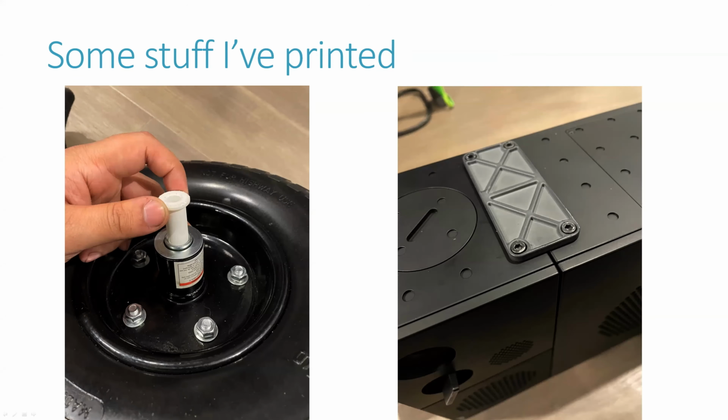And then in the Z, the Form 3, depending on the material you're using, has a few different options for layer height. So you have 20, 25 microns, 50 microns, and 100 microns. And you can choose which one of those works best for your purposes. Generally, we recommend sticking with 100. Even for a high detail part, you'll get better dimensional accuracy with 100. There are some use cases such as jewelry where you can drop it down to 25 to get really fine detail. But roughly 100 microns is your minimum feature size, and that's the easiest way to work around it.